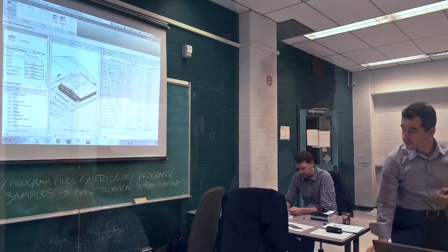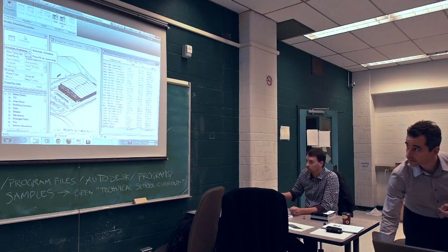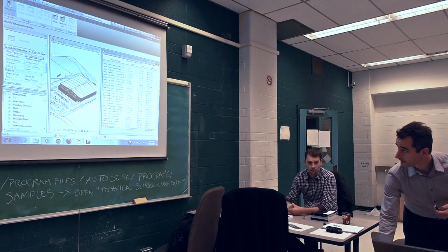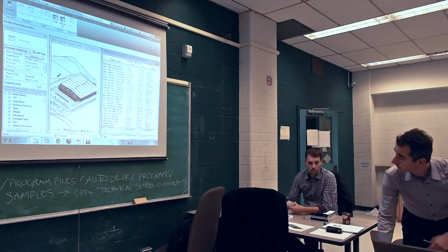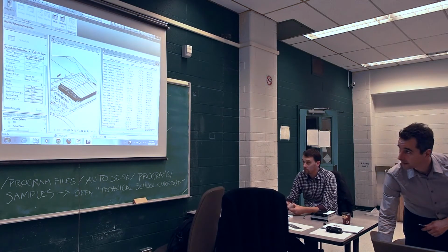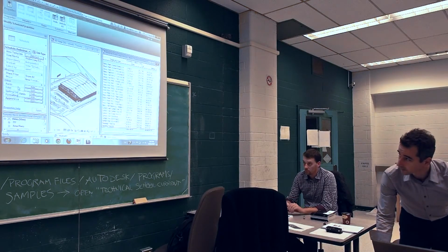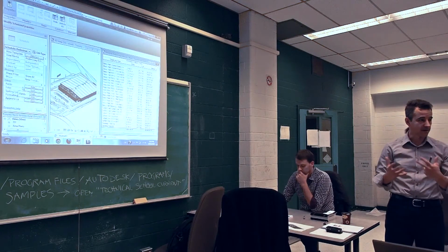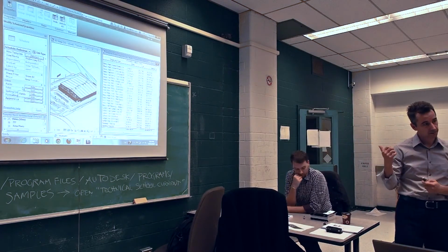Everything in Revit is an object, right? So it's going to have some kind of properties. Even if you open it and you don't have anything selected, by default that's the properties of the view, right? And you will see on the left hand side the type of object and its properties. And if I again click inside my schedule and I drag it down, I have a number of options in here for my schedule, right? Fields, filters, sorting, formatting, and appearance. And all this stuff is really the tools that help me build the schedule.